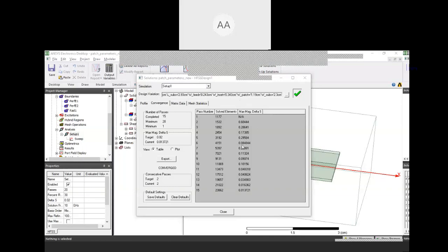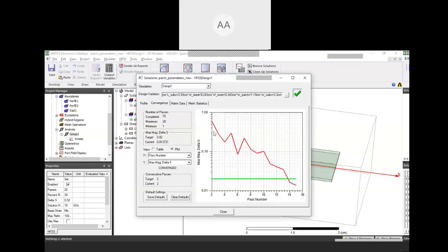Okay, fine. So it keeps on doing this, and what happens? Let's say the number of elements is 23,000, 21,000. It has already come down below 0.02 to the value of 0.10. In the next step, it has increased the number of elements again to see if the values are further decreasing or not. And this can be verified out here. You can see the value should keep on decreasing at every iteration. That is what we are assuming, but it might not be the case. The value sometimes might rise. So after coming below the specified value, it has checked it again, and finally the value is decreased. So that number of elements will be taken for calculation.